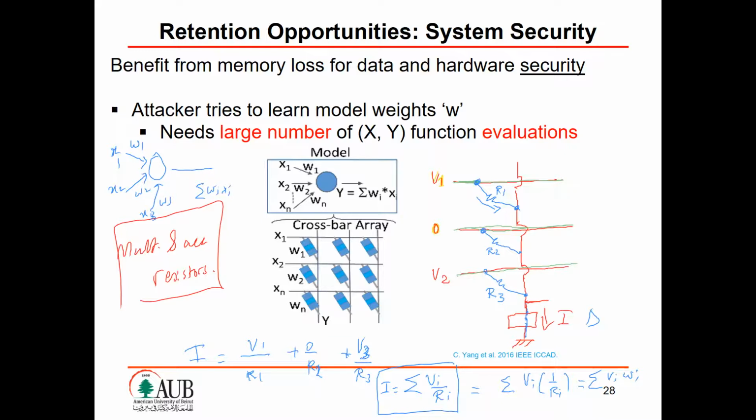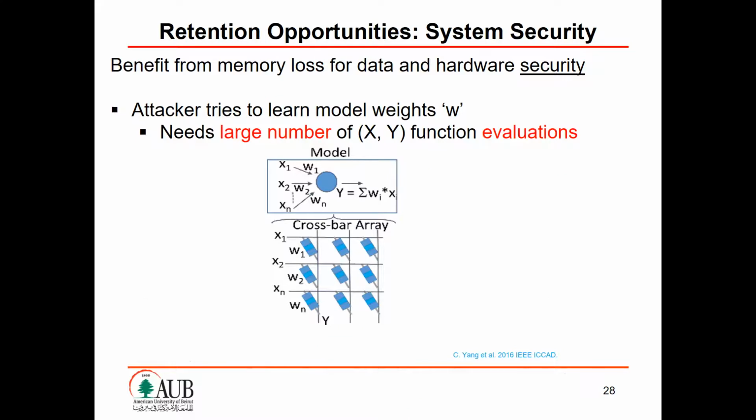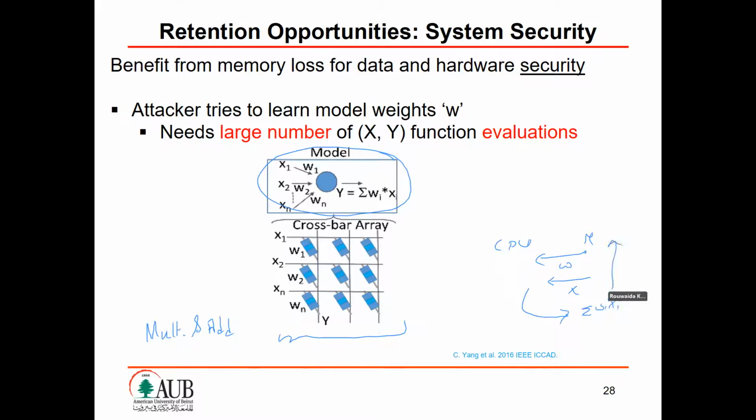Okay? فإذا they demonstrated to us that if we build with these memristors crossbar arrays, we are able to do multiply and add functions. And if we program those memristors to store some specific weight values, then we are able to realize the multiply and add locally without having to write from the memory to the CPU the value of the weight and the value of the x's, and then bringing back the summation of WI XI and storing it in the memory.